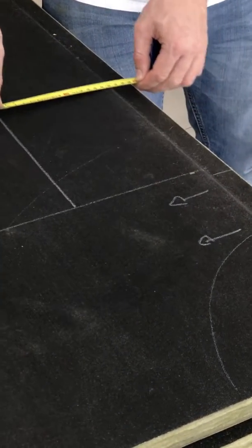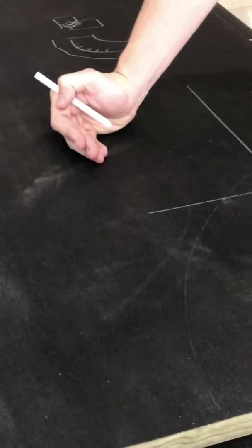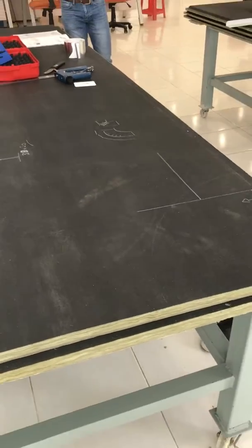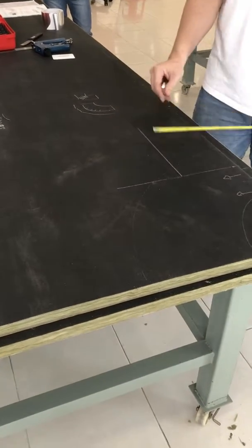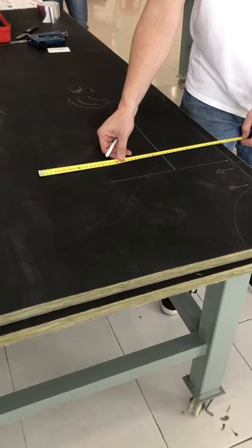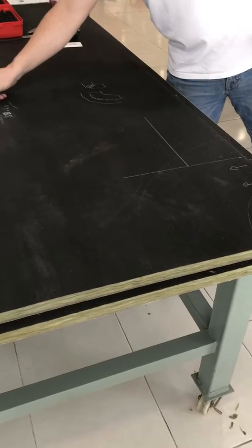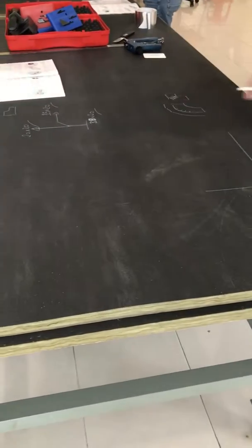Then 20 centimeters, okay? Well, now, this branch width is 15. Remember, if we keep going with an elbow, now I should do 30 plus 2, 32, no? But this is not an elbow. This is a derivation, and here the width is not 30, but it is 15.